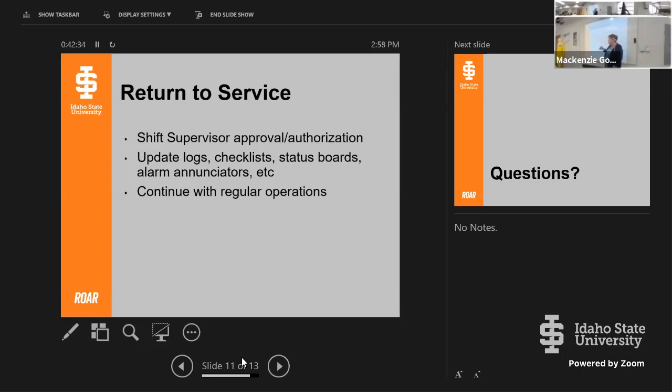And if the conditions down that signal path electronically have not changed, and that same signal that something's wrong comes back, the panel's going to relight up and you're going to get the audible again. But if you've changed the circumstances that led to that signal, you have a system that was offline that's now online, when you clear the panel, you have essentially reset the ability to receive that alarm anew if that system goes out of service, right?